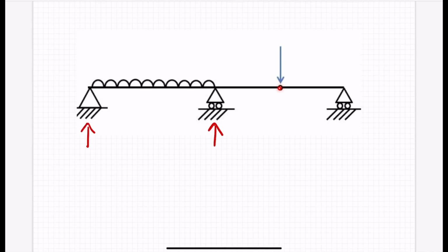But we know this is a zero moment point. Let's say we did have a vertical reaction here; because there's no external force to resist that reaction, it would cause this leg to spin or rotate around that point.